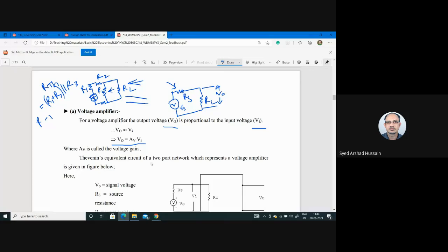So to calculate this equivalent potential, this V, you have to calculate this voltage. You see the voltage drop across this one and this one is the same. So this is equivalent here, same. But if you have resistances in series or other places, then you can calculate the voltage drop using your potential divider circuit. Simple: if two resistances are in parallel, then the voltage is the same. In series, R1 R2 divided by R1 plus R2 into VS. Okay, so this is your equivalent resistance.